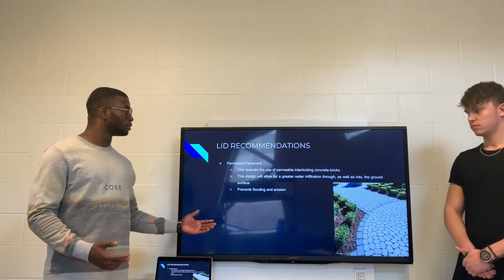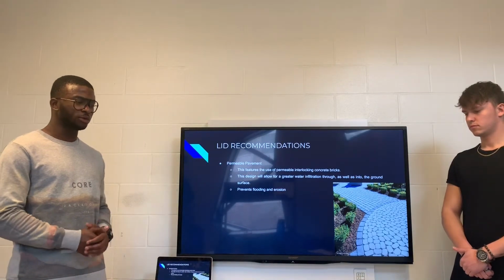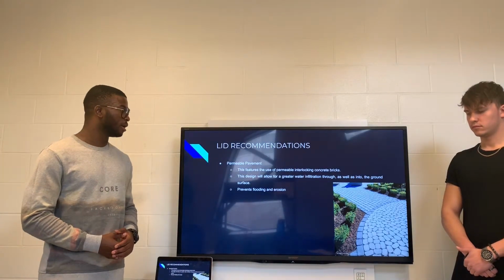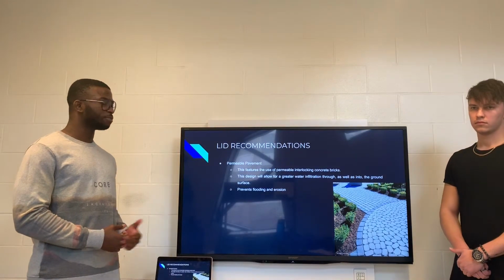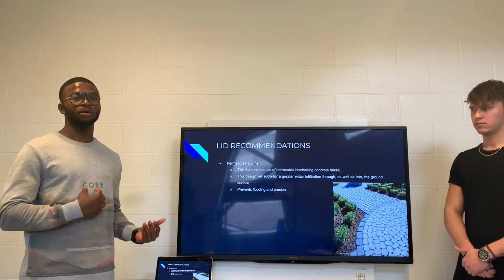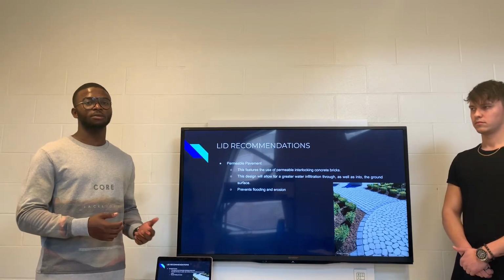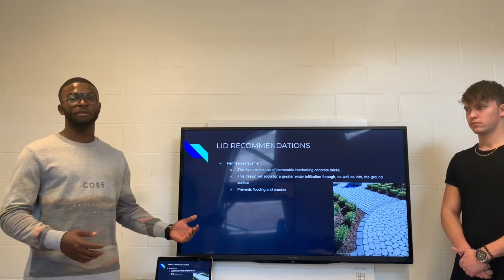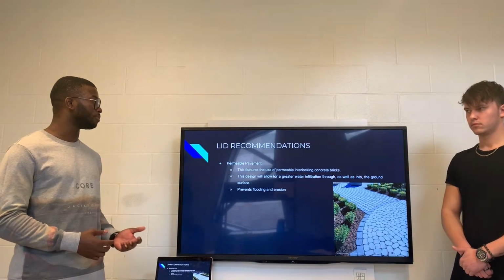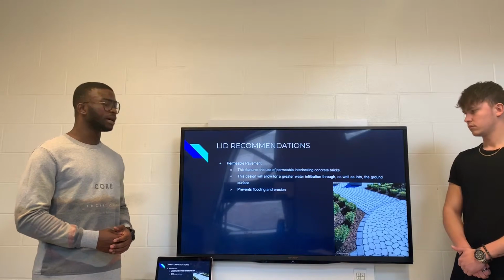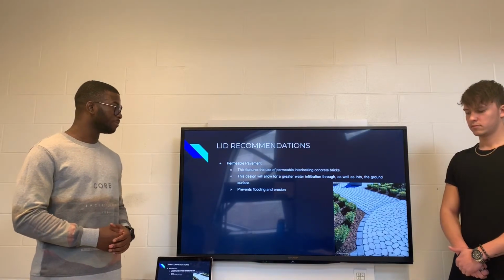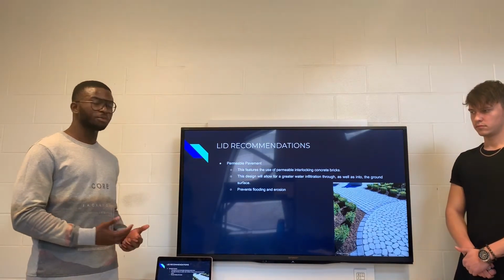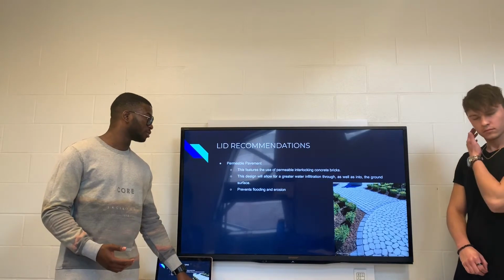Another one was the LEED recommendations which also score points in the LEED checklist, and one of them was permeable pavement. Personally, I remember going across the SEQ building last summer, and they were implementing just asphalt pavements that were totally non-permeable. This interlocking pavement would help with infiltration and would also prevent things like flooding and erosion and things of that nature.